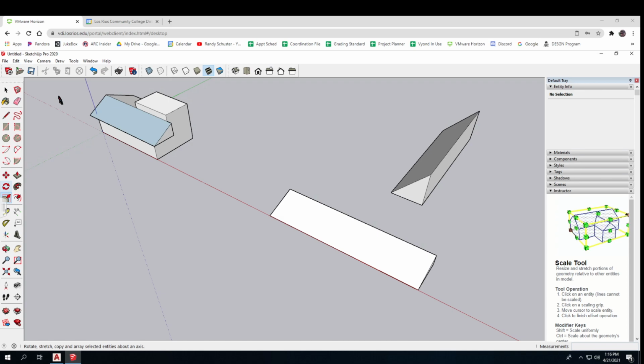Okay, so you've got a 10 on 12. You've got 10 on 12 to the main thing, and then it cuts off and comes 10 on 12 down, right? And then you've got a 4 on 12. So you do have something sort of like this, where you'd have a main 10 on 12 that's the entire piece, it's one whole wedge. Cut your piece out of it and make a new 10 on 12, and then do your 4 on 12 roof and put it up against it.